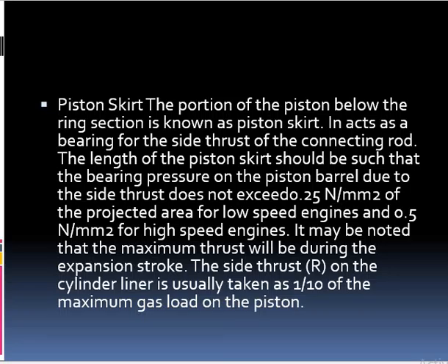It may be noted that the side thrust during the expansion stroke, which we denote by capital R, on the cylinder liner is usually 1/10th of the maximum gas load on the piston. Maximum gas load on the piston.